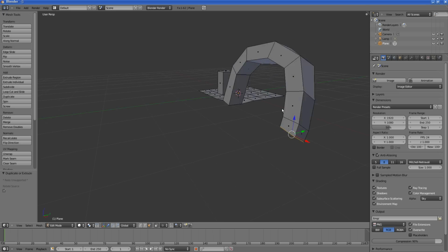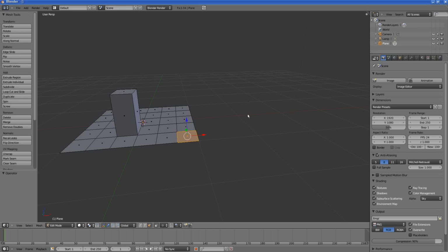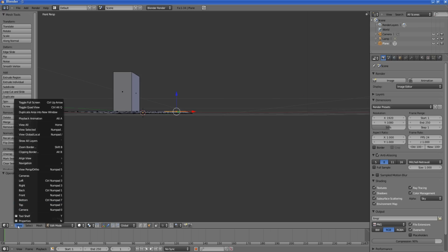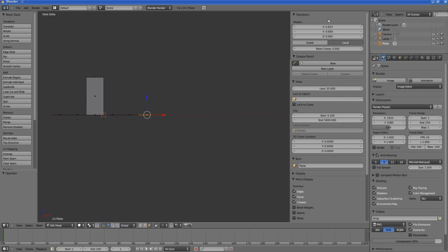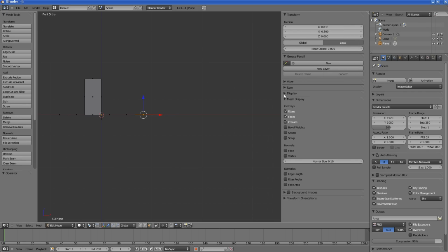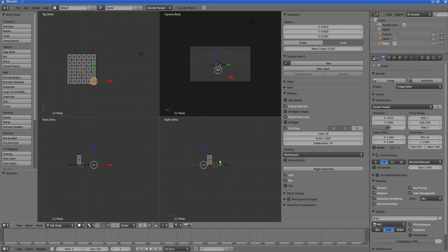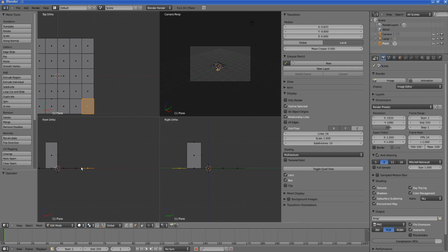If you want to place proper extrusions, let's undo, Control Z, switch to the front view, switch to the orthographic view. Now I'm in the front view. Select the face. You can also use your quad view layout for better control. Quad view and box. So now I can add an extrusion in the front view.